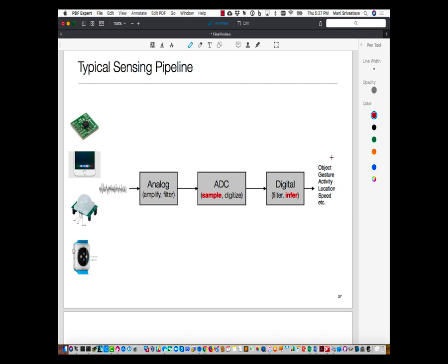Then we had compressive sampling, which relied on the fact that maybe I can make additional assumptions about the signal. The example I walked you through was, imagine I knew it's a sine wave. A sine wave only has 3 parameters: the amplitude, the frequency, and the phase. So what I'm seeking to do is collect enough samples so that I can estimate these 3 parameters accurately. That would be sufficient for reconstruction.